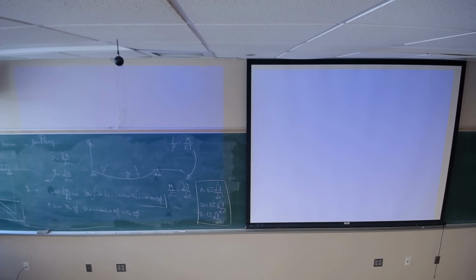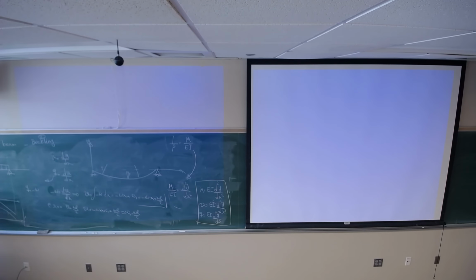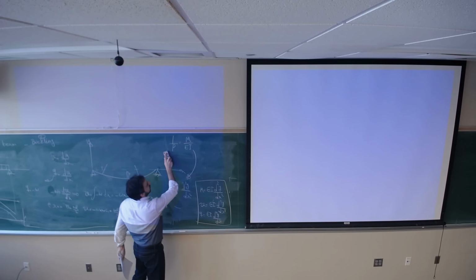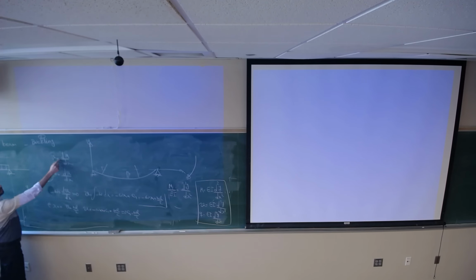So shear force is going to look like this. You can get this equation, this line, by the approach that we covered in chapter 3: just cut the beam and write the equilibrium equation to find the shear force. This is another way that you can derive the shear force. Now I'm going to get the bending moment by using this equation.